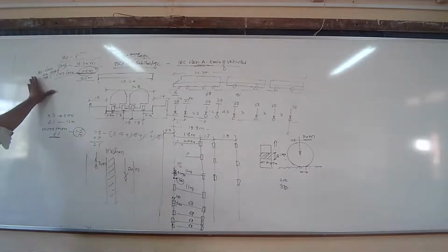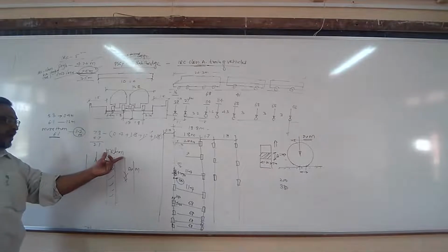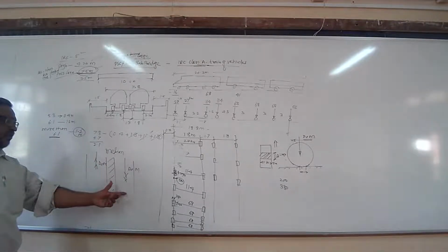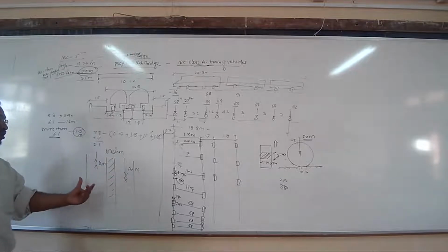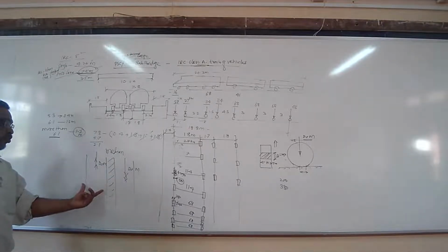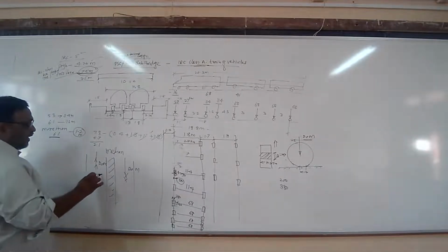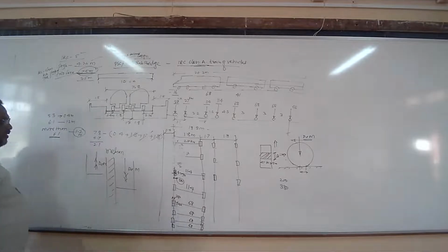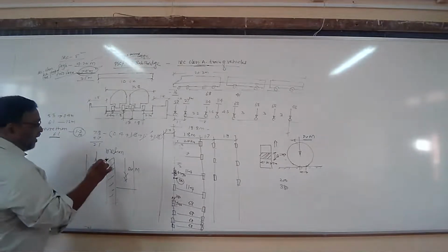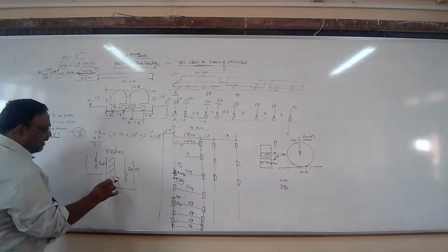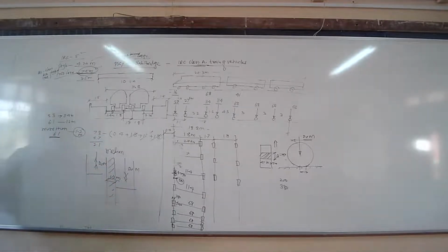ये सब IRC में दिया है, where the median is provided, on each side of that when the motion of the vehicle is in the opposite directions. So in that case, minimum 2 lane road must be there on either side of the median. ये कम से कम 2 लेन का रहना चाहिए, ये भी 2 लेन का रहना चाहिए. Plus median must be minimum of 1.2 meters. That is given in that IRC 5.